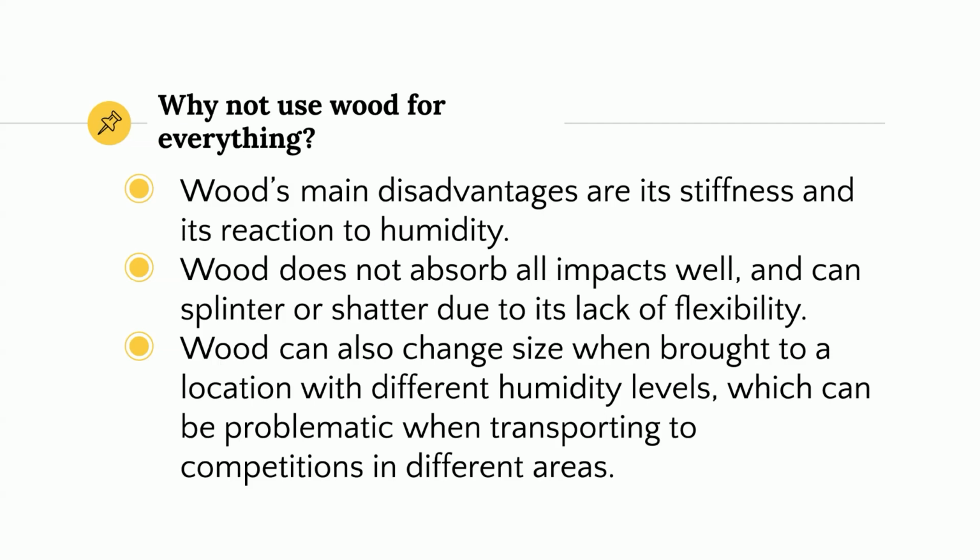However, wood can also change size when brought to a location with different humidity levels. This is very problematic, especially when you're going to competition, because sometimes you can travel a very large geographical distance for competition, and the wood within that robot can change its size by half an inch or an inch for each piece of wood, which can completely change the way your robot functions, sometimes even breaking the robot. This is all due to humidity.